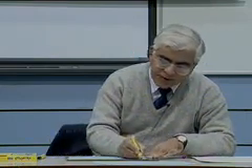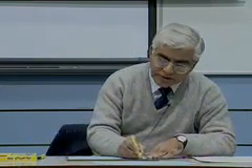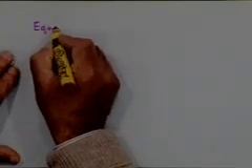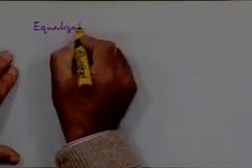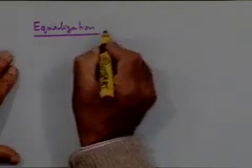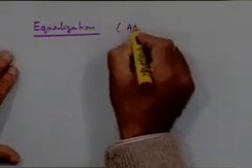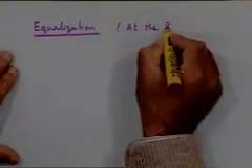It's obvious. What should we do at the receiver? Put a filter which is a reciprocal of the channel transfer function. So in theory it is possible to remove linear distortion through a process called equalization, and that will have to be done at the receiver.